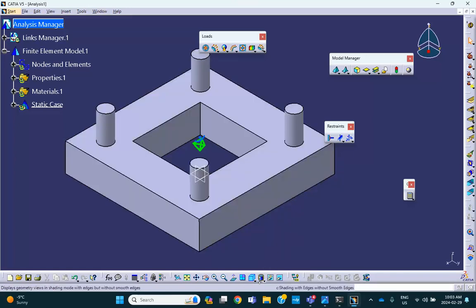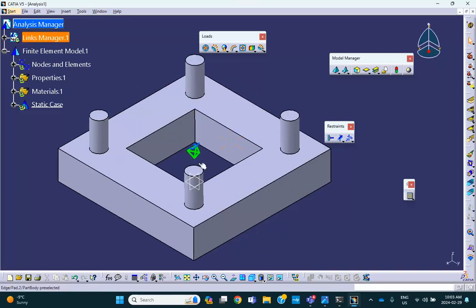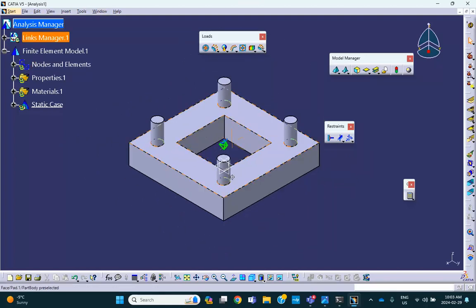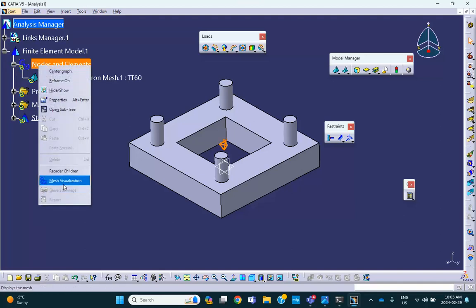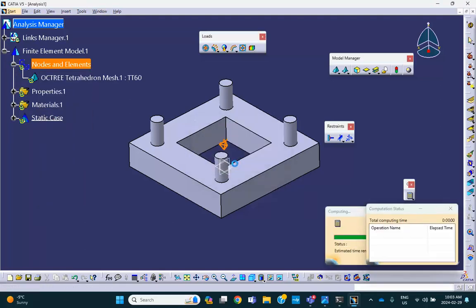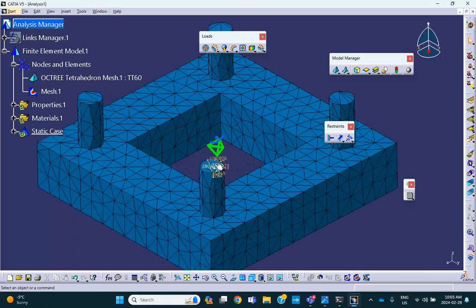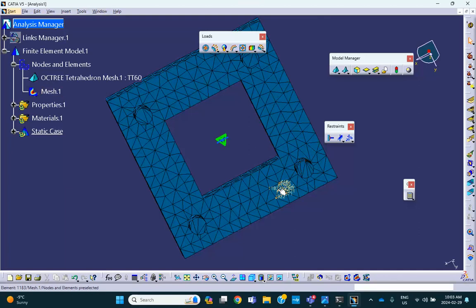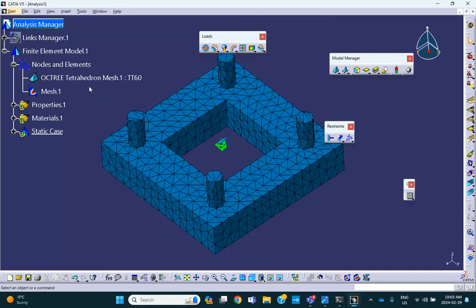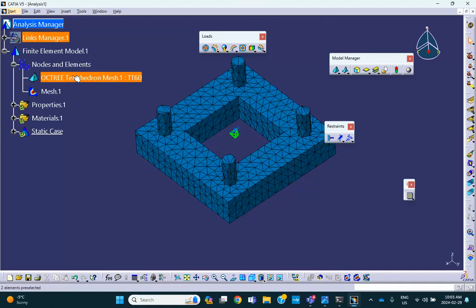Here's the rendering icon. Now this is a very large element because I can mesh it, but you can see that it's going to look ugly. If you look at the top of these things, these are meshed with elements which are highly distorted. So what I'm going to do instead is change the mesh size. This piece is okay. That piece is okay. What is not okay is the stuff up here.